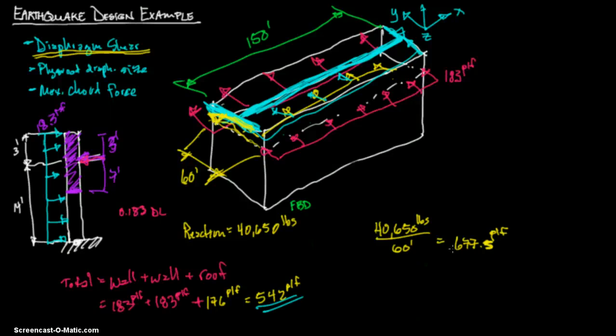23-I-J-1, allowable shear in pounds per foot for horizontal wood structures, panel diaphragms with framing of Douglas fir, larch, or southern pine. That's a long title. Anyways, we go down, so we're looking for anything greater than 677 or 678, let's say. So we go down, let's look at a common nail size,